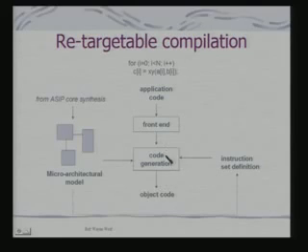And then you generate the code, because this instruction set definition also comes from here. So you make use of the instruction set definition, look at the microarchitectural model, and then look at the object code. Now, if you are doing a design space exploration, it means that you have the object code, execute the object code, get the performance estimates, go back, modify the microarchitectural model, modify the code generation, and again try it out. So if you are doing this kind of soft core based development or platform based development, this is one way to do design space exploration.